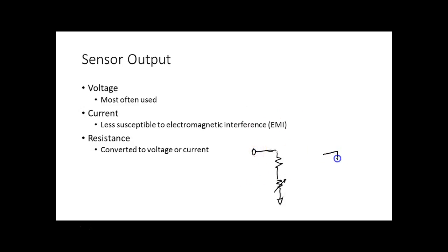So if I came over here and took that sensor and did it like this, you understand? Then what we would be doing is changing a current, but we wouldn't be changing the voltage. You understand that? Yes or no? If I put a fixed resistor in series with it, then when this guy changes its current, it's going to cause this guy to drop what? A voltage. And then now this guy's going to drop a voltage.